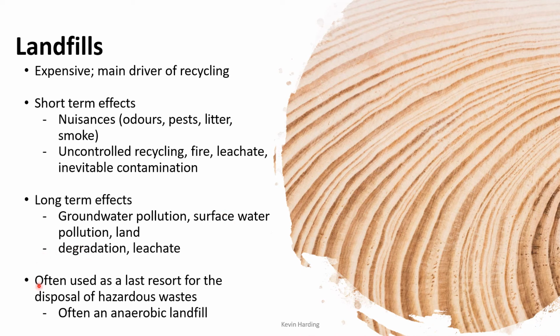Okay, this is often used as a last resort, particularly for hazardous materials. There are certain hazardous materials that you can't do anything with, and you have to landfill them. If we don't want those hazardous materials to get into the groundwater or into the leachate, these need to be put into sealed containers. Depending on how dangerous or hazardous they are, they're sometimes even put into concrete slabs. So you not only have a hole in the ground, but you have to put your hazardous material in a container, in a concrete container. So it's taking up quite a bit of space to get rid of whatever your hazardous material might be.